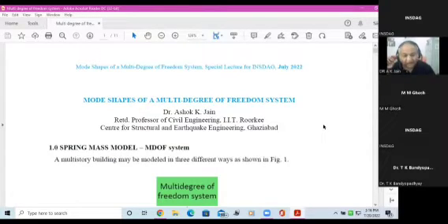Okay, thank you. Now, as far as this 1893 code is concerned, it has three features built into this code. One is it tells you what should be the shape and other characteristics of a building, that is in terms of mass distribution and stiffness distribution. Second aspect is it tells you how to calculate the earthquake force on a given building at a given site, that means in a given seismic zone. And thirdly, it tells you how to analyze the building for a static case as well as for dynamic case. So these are the three distinct areas which are covered in this 1893 Part 1 code.